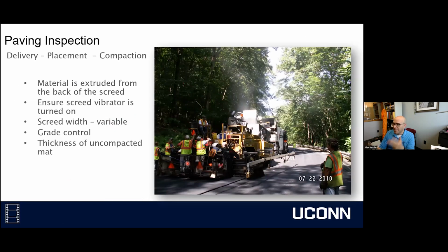So the material gets extruded from the back. The vibrator on the screed helps give it some initial compaction. There's also a heater on the screed so the material doesn't stick. There's a lot happening on the back here, and you can actually see there's computer controls. There's a whole host of things happening right on the screed.